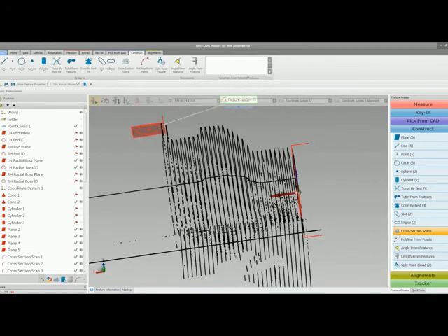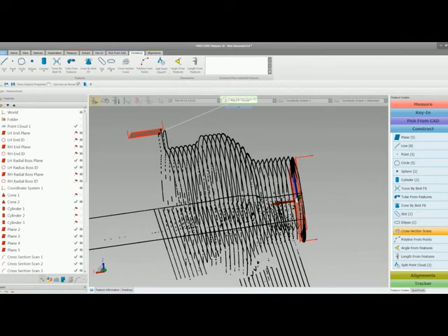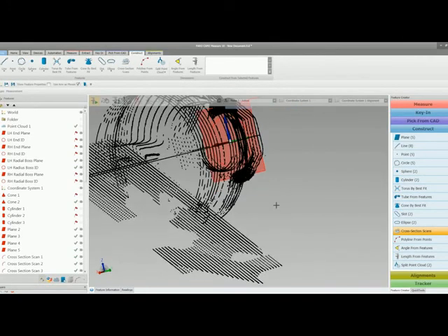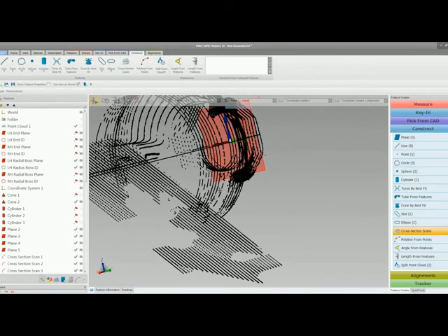The nice thing about revolving the part, particularly circular parts like this, is that I don't need to have all the data that's down here. In order to scan this, I would have to fixture it so I could see all the way around it if I was going to use some of the reverse engineering packages that are available. But if I'm just going to revolve this section, I just need to scan it along one section and know I'm going to be good to go.